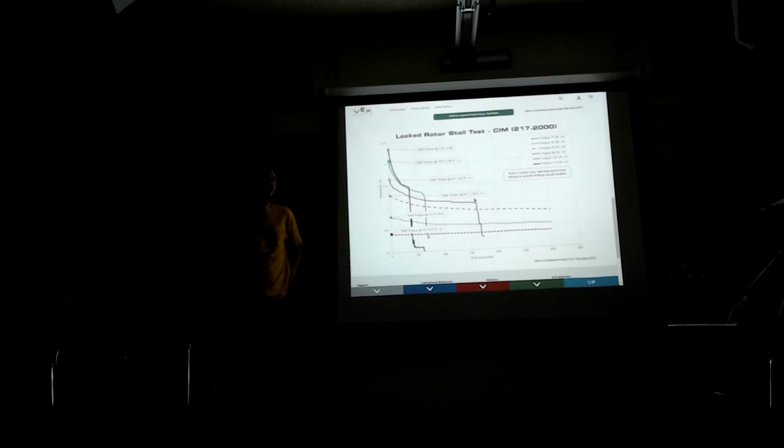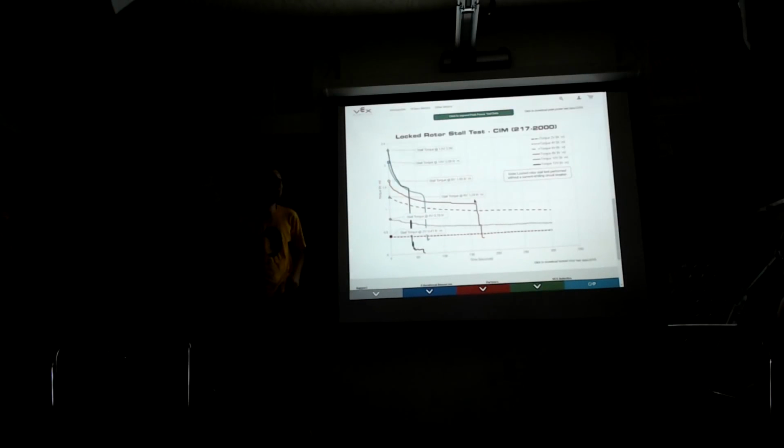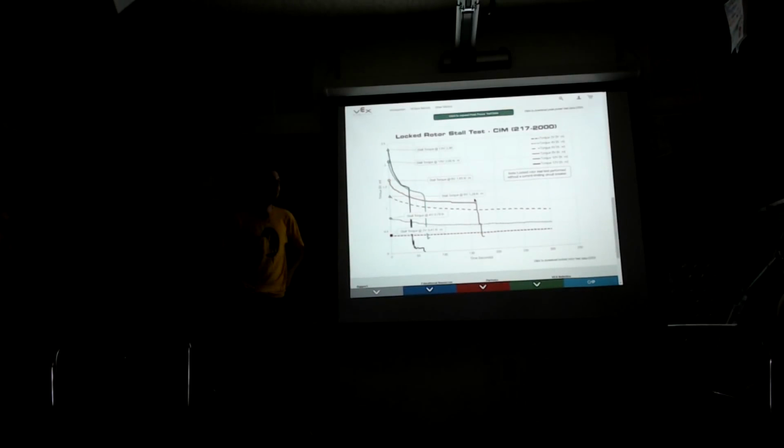Other questions? If you were to take into account the efficiency of the gearbox, where would you add that factor into the equation? It would reduce the output torque, so you would just append it to the torque. I would scale it. I would take the torque and multiply it. What he's getting at is gearboxes aren't perfectly efficient. If you put a torque in, you don't quite get it out. There's a little bit of friction, and that steals some of your torque and some of your power.